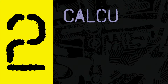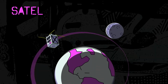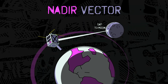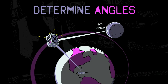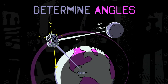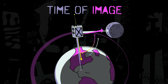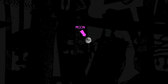The second step, calculate the time of image by defining the relationship between these key vectors. 1. Determine the satellite to moon vector, which points directly from the satellite towards the moon. 2. Determine the NADIR vector, which points directly from the satellite towards the center of the Earth. 3. Determine the angle between 1. the satellite to moon vector and the NADIR vector, and 2. the angle between the satellite negative Z vector and the camera body vector. The instance when the difference between the two angles is minimized gives us the time of image, the moment along its orbit when the satellite will be in position to take our all-important moonshot.